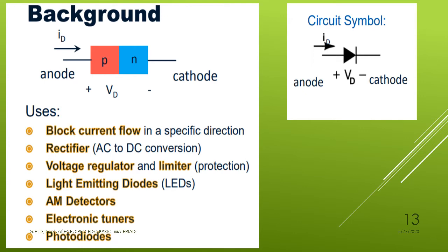What is meant by a rectifier? Whenever it acts as a rectifier, it converts AC to a pulsated DC. AC means alternating current, converted into direct current, but we won't get pure direct current at the output of the rectifier. Definitely we have a pulsated DC, which can consist of some AC components in the DC voltage. That we call pulsated DC. Because of that, we can make use of filters at the output of rectifiers in order to minimize the pulses present in the DC.